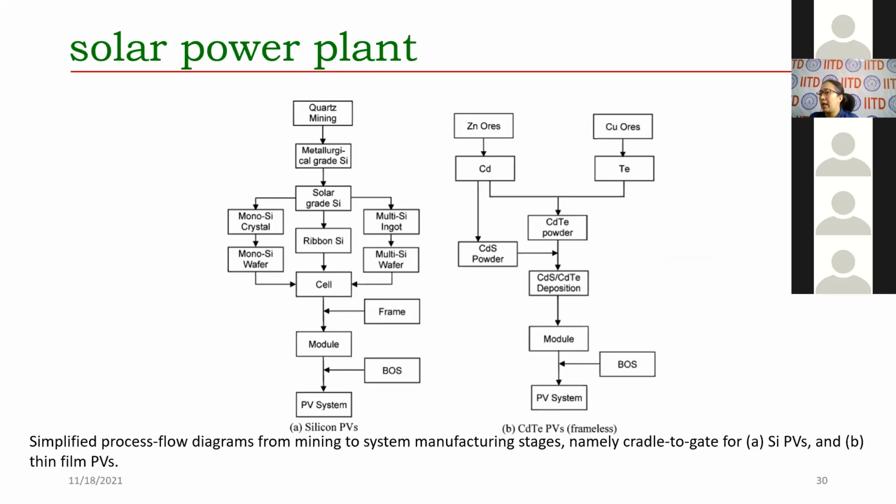So if you look at the solar power plant, if you want to do a life cycle analysis for it, we see whether over its entire life, this is what life cycle means, and normally we assume that the solar module that we see has a life of about 25 years, 20 to 25 years. So even if we assume, let's say 25 years, that is the maximum, how much energy has gone into it to manufacture it, to source these materials, the emissions that have gone into it, and how much does it produce, right? How much electricity it produces over its lifetime, and all the emissions and everything are loaded on that production. So if it produces X units over 25 years, then all the emissions are loaded for those X units, and per unit is calculated.